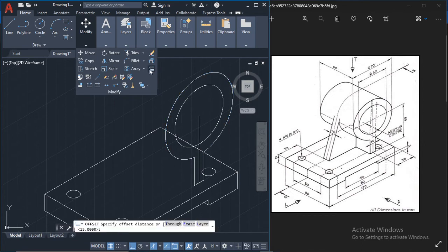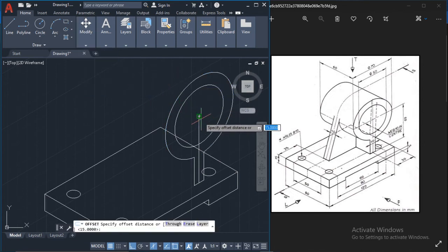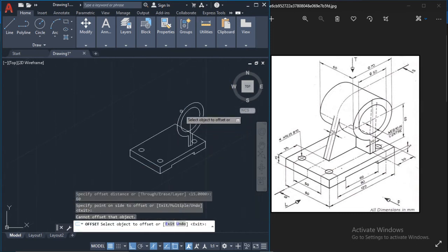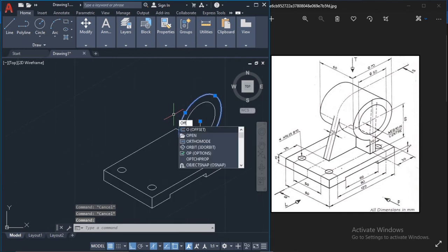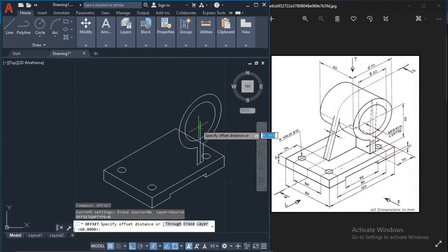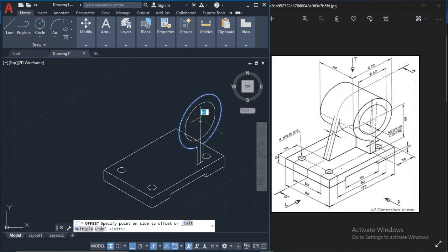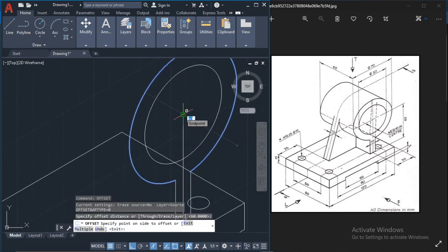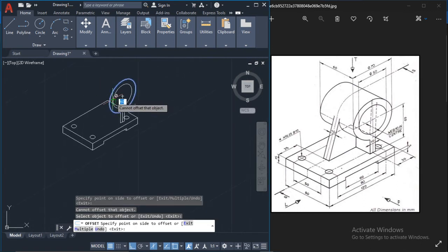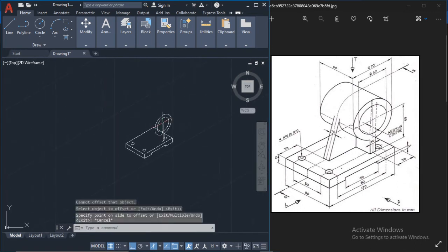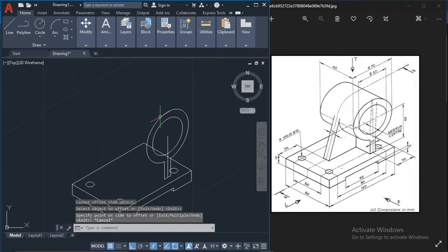here. Specify distance 60. And from here, oh, sorry. So I'll click on the circle, type offset, specify distance, that's 60, and I'm going to select from the center of the circle. All right, that won't work, so I'll just do this instead. This is what I'll do instead.